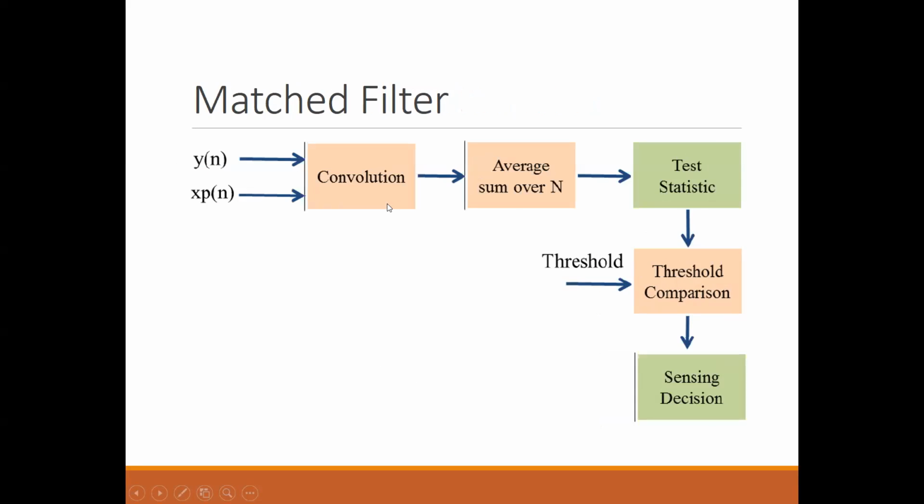Right? And again, the matched filter, of course, the term implies: you have a copy of it, you just match it to that and see. So the matched filter can be implemented as a convolution filter. I hope you might have come across the matched filter on several occasions in digital communications. Essentially, the matched filter is for, given a signal, say you want to detect that. So you design a filter whose impulse response is matched to that particular incoming signal. What is meant by matched? You just flip it and shift it by a factor of t. That is how it is matched.